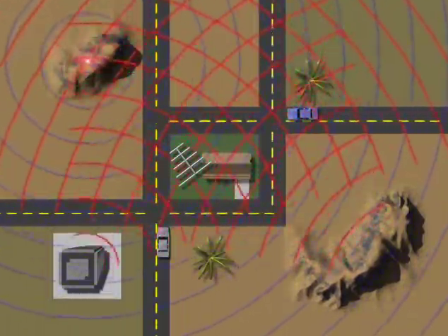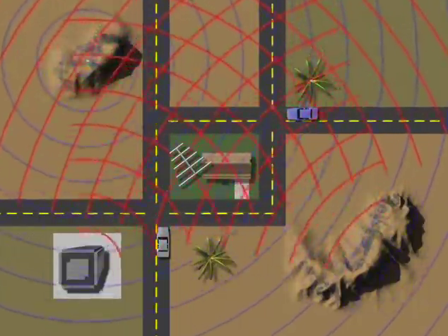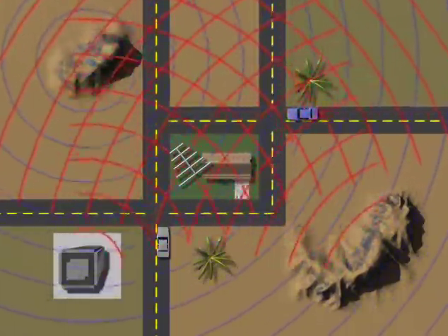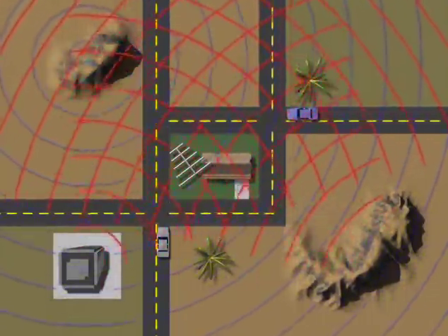Several reflected signals can arrive from different paths, each delayed a different amount depending on how far away the reflecting object is. The echo signals show up as ghost-like images to the right of the directly received signal. There are several ghost images in this picture indicating several multipath signals. The delay or displacement of the ghost indicates the relative distance from the receiving antenna of the reflecting object.